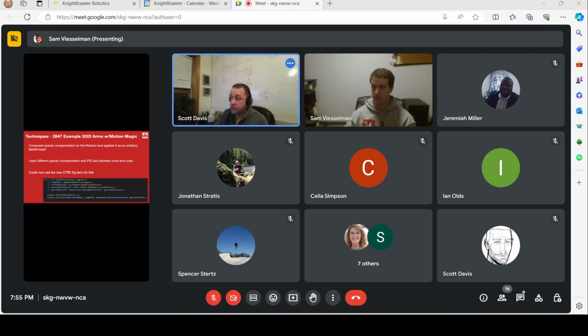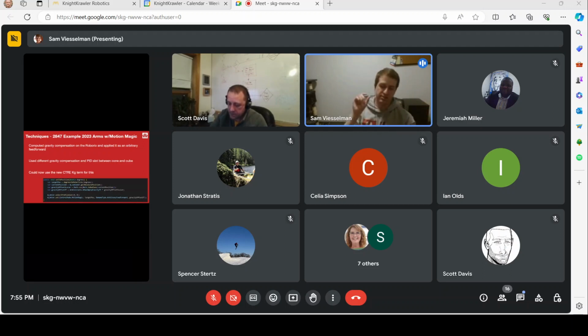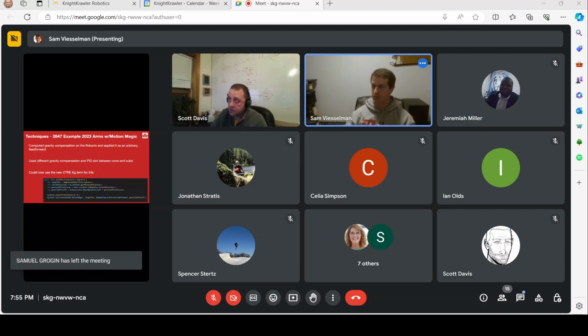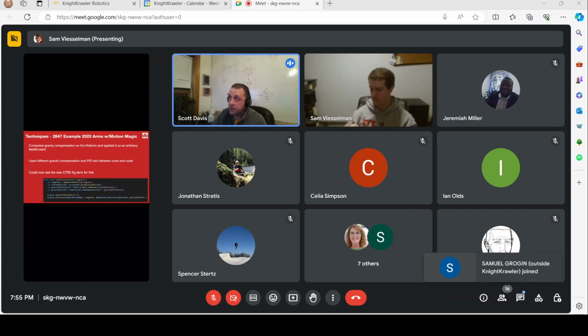And so the F would be in terms of number, a voltage then in this example? Yeah, it's really a voltage times the error. So KP in this case, the units of it are the error, right? You're off 2,000 ticks. So 2,000 times your KP is going to be how much voltage you apply. And if your P is 1, that's a lot of voltage. You're not going to be able to apply that much voltage. That's right. Yep.